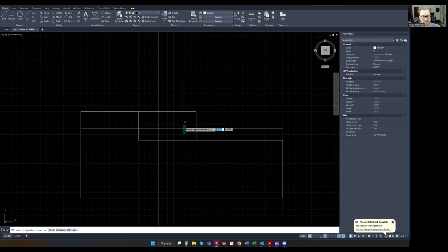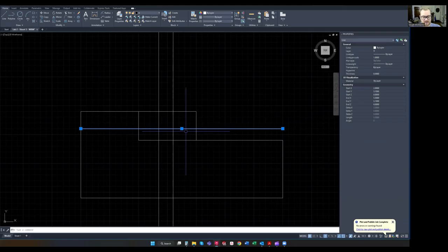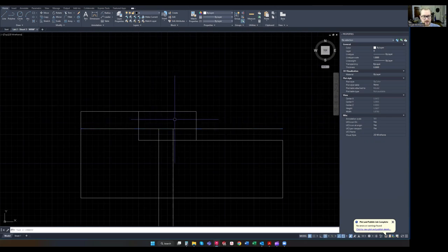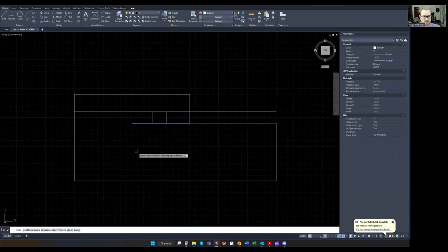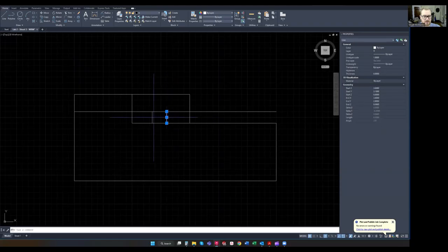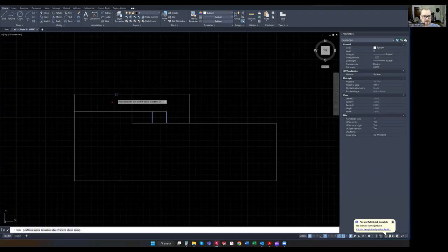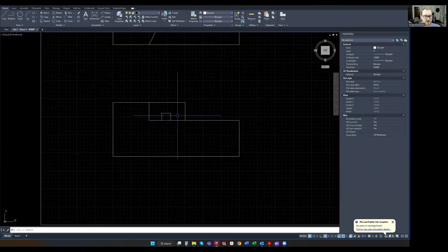And with that, I'm going to use the more advanced trim tool. So I'm going to highlight this line, TR, enter. And then you can just click them, or you can just kind of click, drag like that. That's fine too. I'm going to use that advanced trim tool again. I'm going to highlight that line, TR, enter. Trim below, and then I'm going to grab both of these, TR, enter, trim this line out to this right, and trim this line out to the left. And what we're left with is our little square here, a little box.